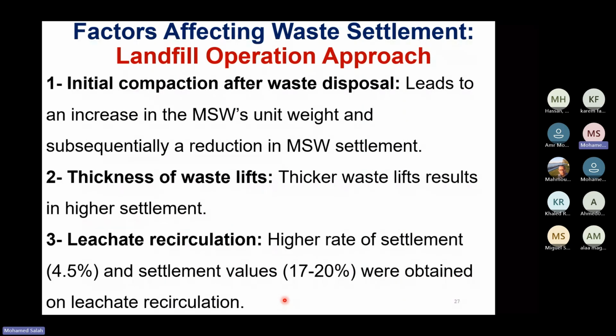The initial compaction of the waste leads to an increase in the municipal solid waste unit weight, and as a result, the settlement of the waste will decrease, similar to the compaction of soil. The thickness of each waste lift placed inside the landfill affects the settlement also. If the operator tends to place a thicker waste lift, this will lead to higher settlement. Finally, we can get a higher rate of settlement and settlement value if the leachate inside the landfill is recirculated.